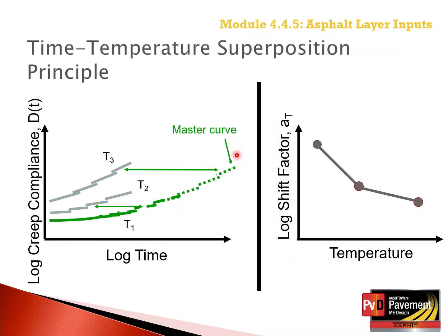The PMED software uses the principle of time temperature superposition to develop a creep compliance master curve for the wearing surface mixture. In concept, use of the time temperature superposition principle discussed for dynamic modulus is the same as for creating the creep compliance master curve.